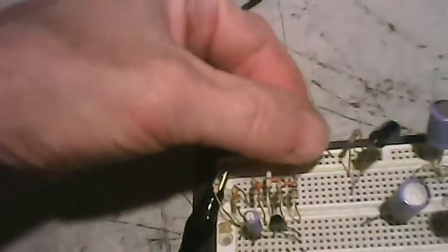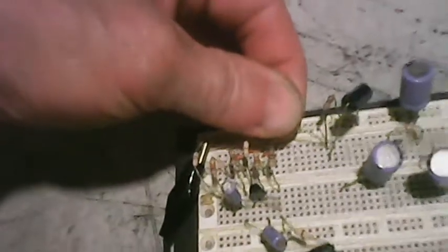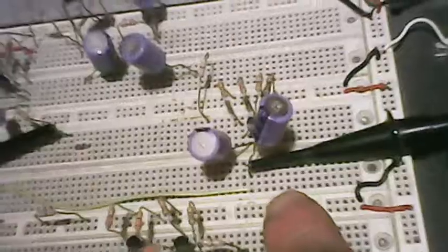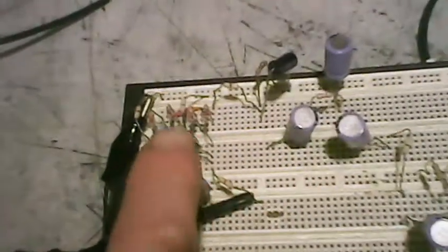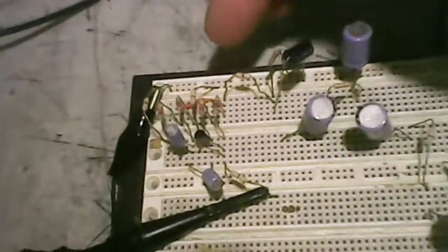So I'll take this and move it over to the low pass filter now, and let's look on the oscilloscope. It's completely gone, and there's the waveform now off the power rail. This is the power rail that the amplifier is picking up, and we can see that the parasitics on the power rail are down to a minimum. So now we have decoupled the astable multivibrator from the power rail.